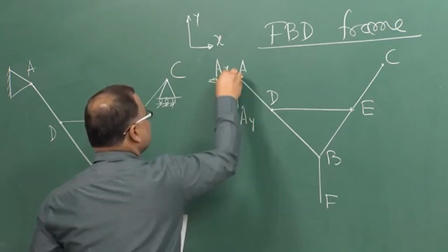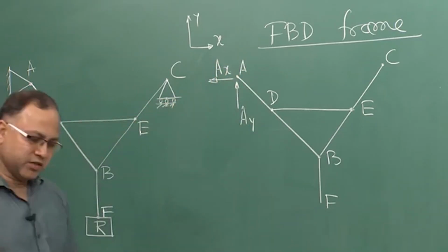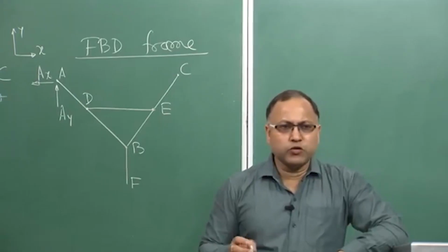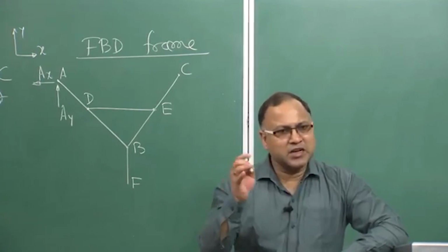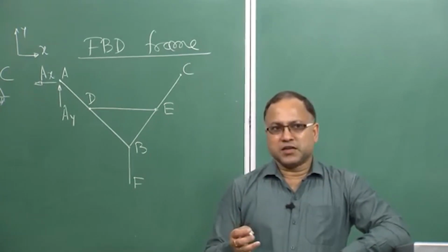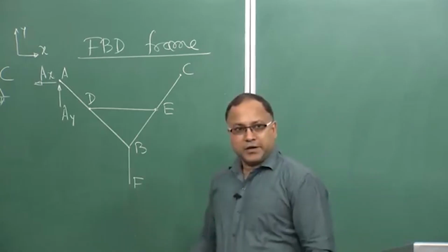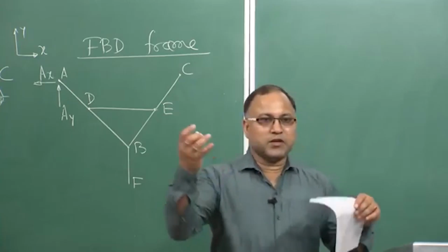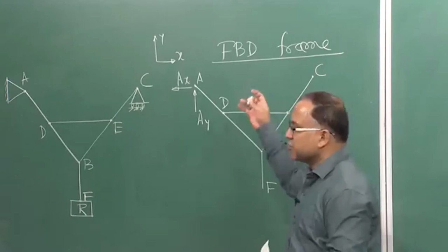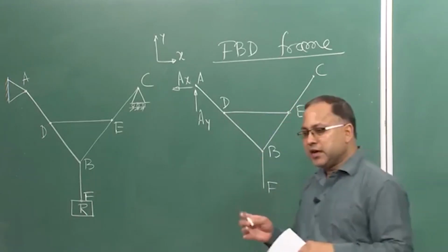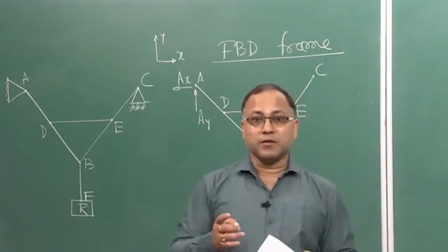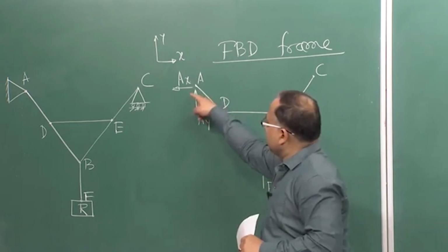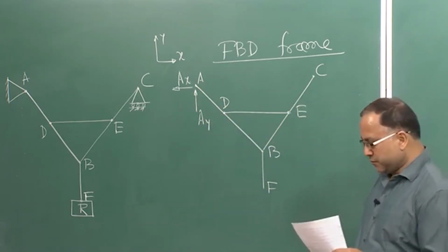You may ask me why I am showing Ax in this direction. Let it be in the opposite direction, I do not have any problem, because I do not know the actual direction. That will come later on when we will be actually analyzing the structure, the correct direction. So, right now this direction is arbitrary, I am just putting it arbitrarily. You can choose different directions, there is no problem, but we will come to that point. So, we are replacing the reactive forces here.